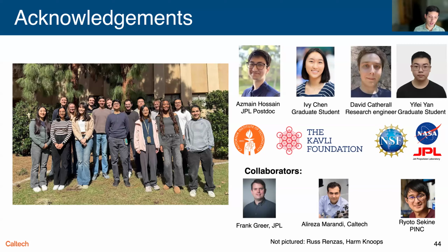Yeah. So the directionality depends on the process. In some cases there just isn't a way to get it, but in the lithium niobate HBr process I showed, you can do it in the ordinary way you do with RIE, right? You can tune the ion angle distribution to make it more or less isotropic. So it's the same concept here.